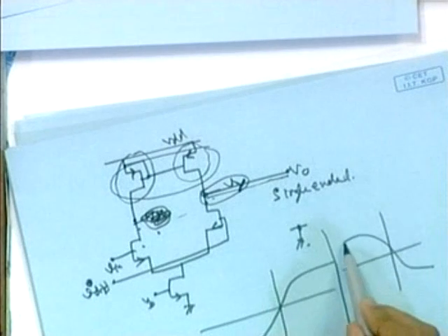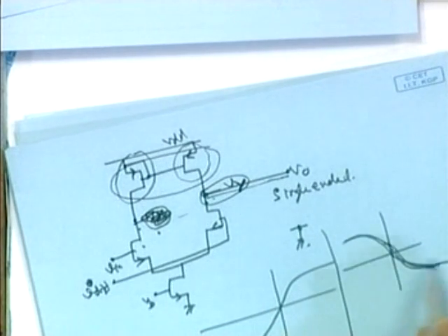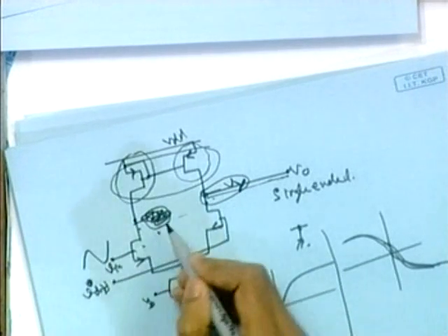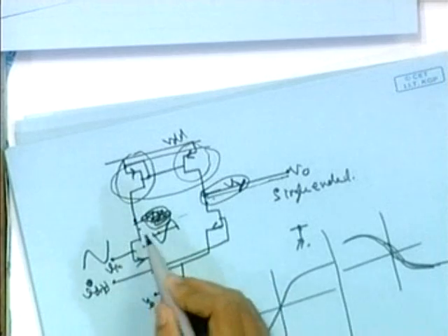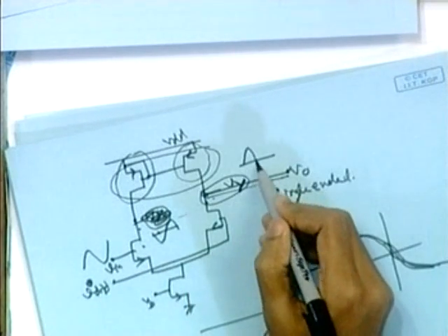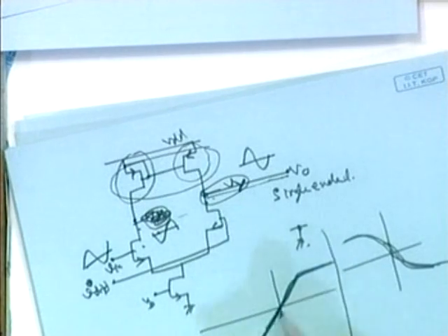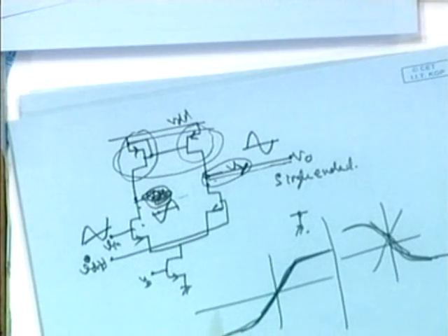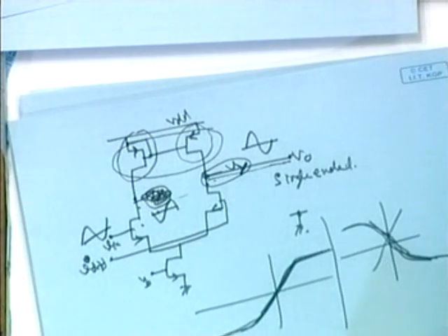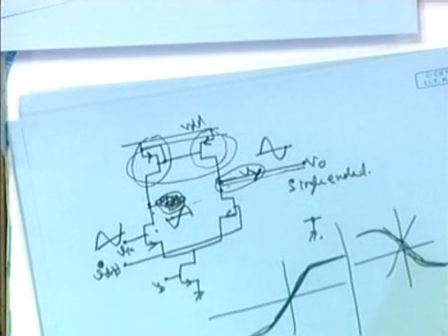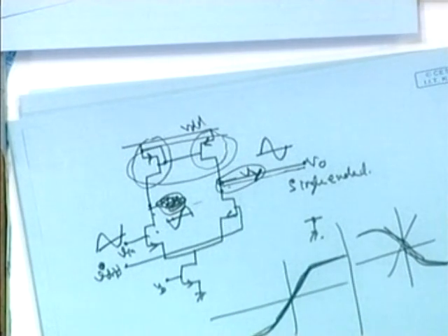And for the rest of the transistors we have this one, the rest of the diffs. But for this we will be lacking, because the input here is increasing and here it is decreasing, so it will be inverted, and here it will again be the same thing. So we are getting a non-inverting output here, so positive gain. The transfer characteristic of this will look like this one, not this. So this is your current mode acting.